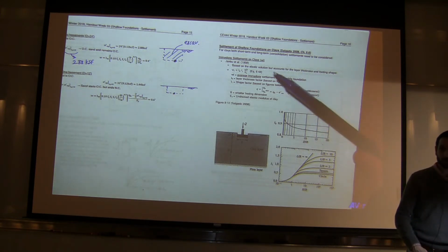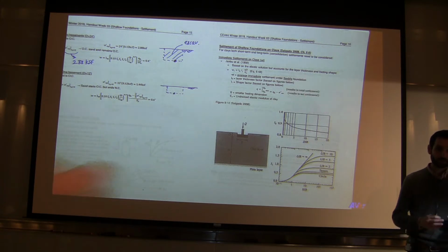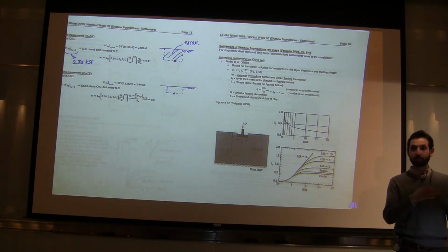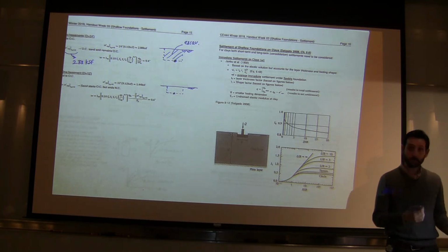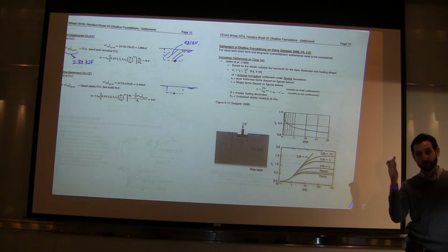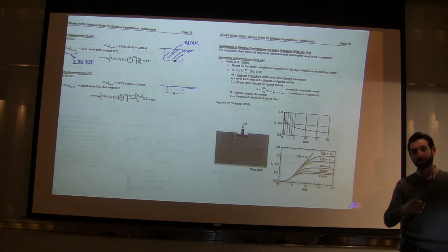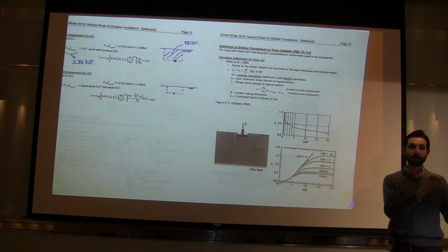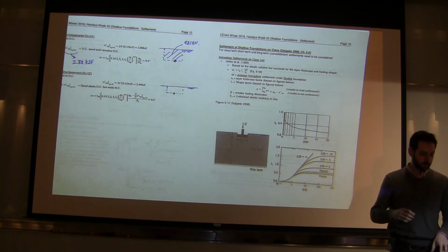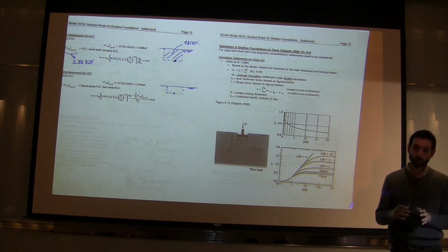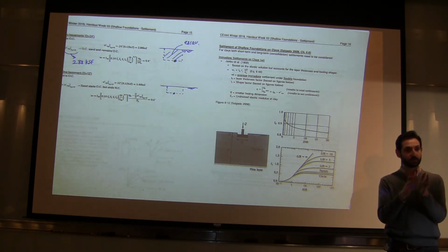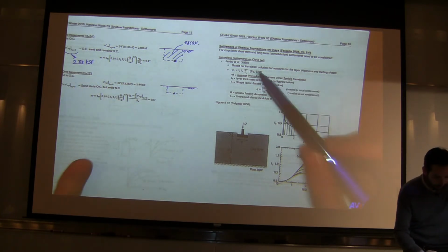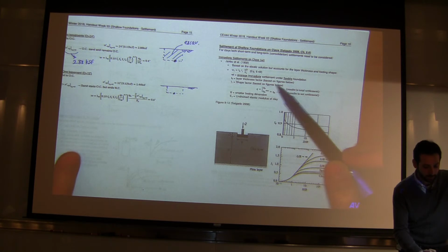But the Janbu equation for clay, these are elastic solutions, so we can really separate them into flexible ones and rigid ones, and for flexible ones we can look at the edge of the foundation, the center of the foundation. But for us as designers, we've passed those conceptual elastic solution designs. Now we're getting into the practical equations. The sand equation is a practical equation. You plug in the numbers, you get the settlement, you report it to the structural engineers. This one, same thing. It's a practical equation. So they've averaged the settlements at the edge and the center, and they came up with this W_I, the average immediate settlement under flexible foundation.